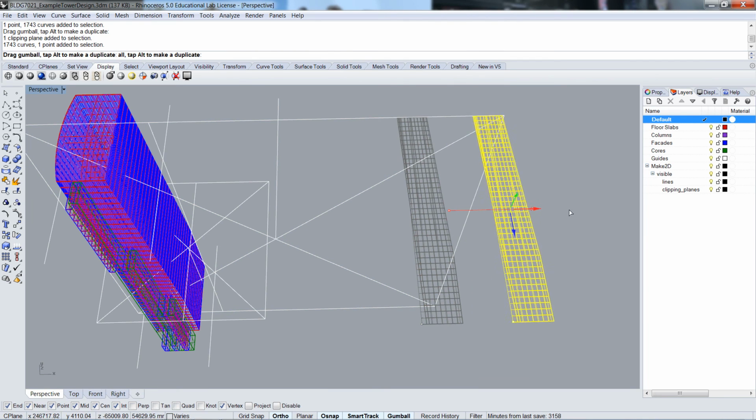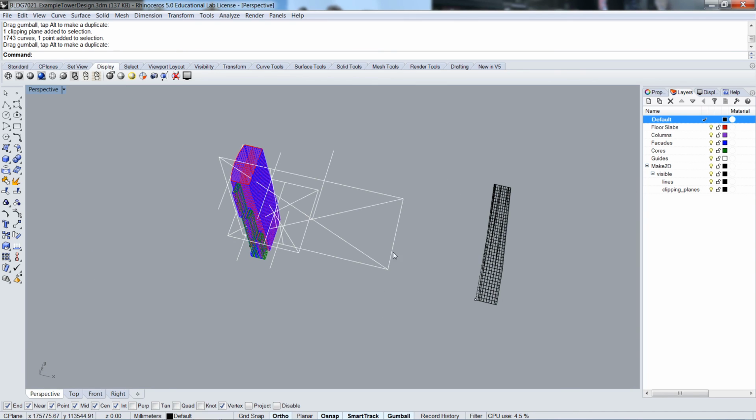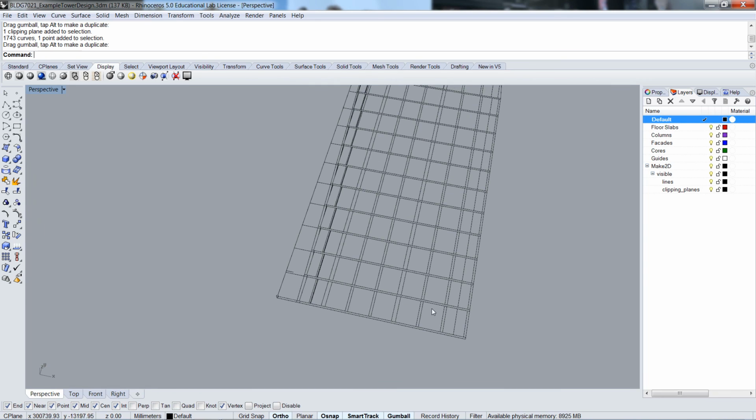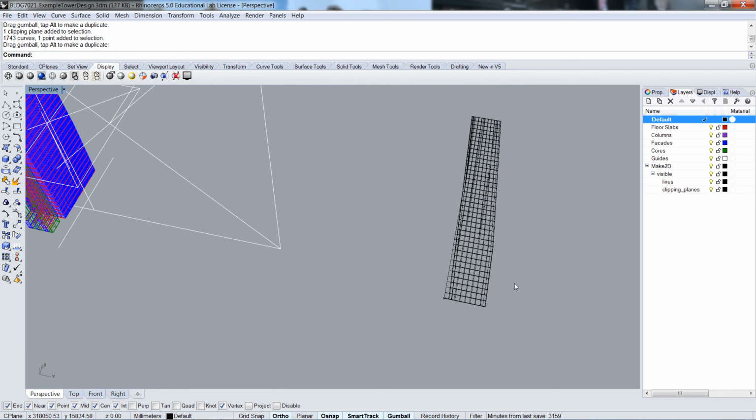I'll just drag this further out of the way. And then once you've got them all, they'll all line up on the plan surface. You can then export that as a DWG and bring it into Illustrator or another CAD program. Now, don't underestimate the time it'll take you to go through and then edit all of the line weights to make this more intelligible, but with the base geometry there, it'll give you a good start.